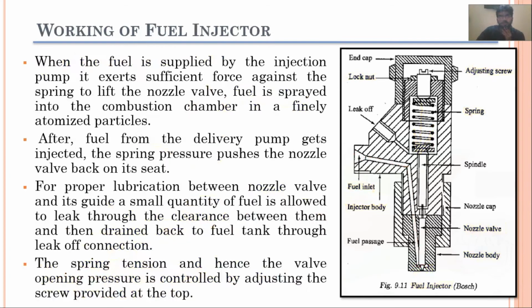Now moving forward, I have already explained the working of the fuel injector. I will briefly discuss this working again. When fuel is supplied by the injection pump, it exerts sufficient force against the spring to lift the nozzle valve.